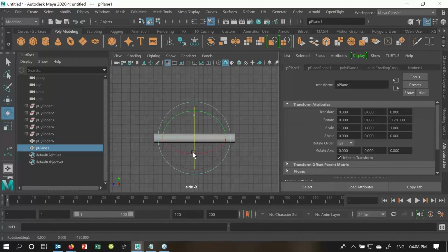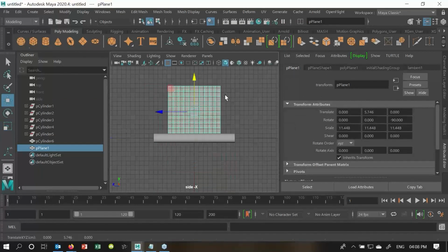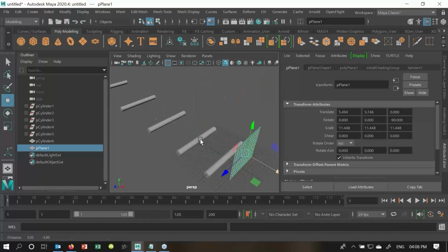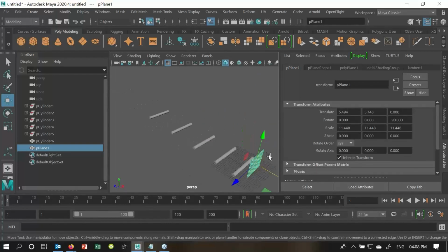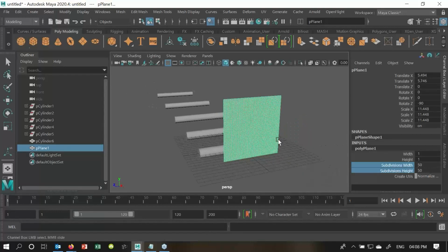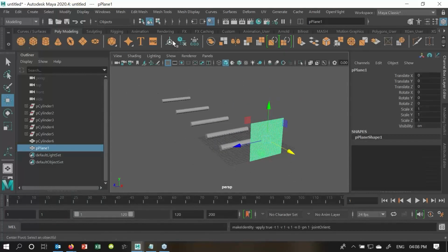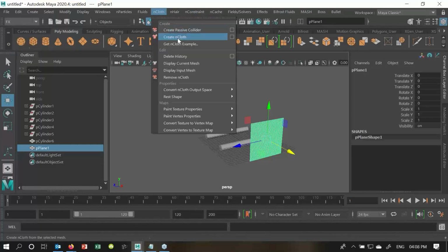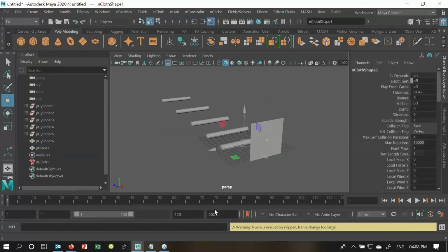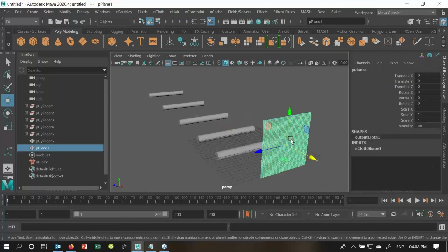See, we are using a different process to understand the different features that are available, because within a very short time we are getting a very good result. I'll select and just drag it, increase my speed, right? I'll just move this, select your object, go to the FX, cloth and cloth. If I start and play, I'll increase my time duration, play over here, this will fall down.